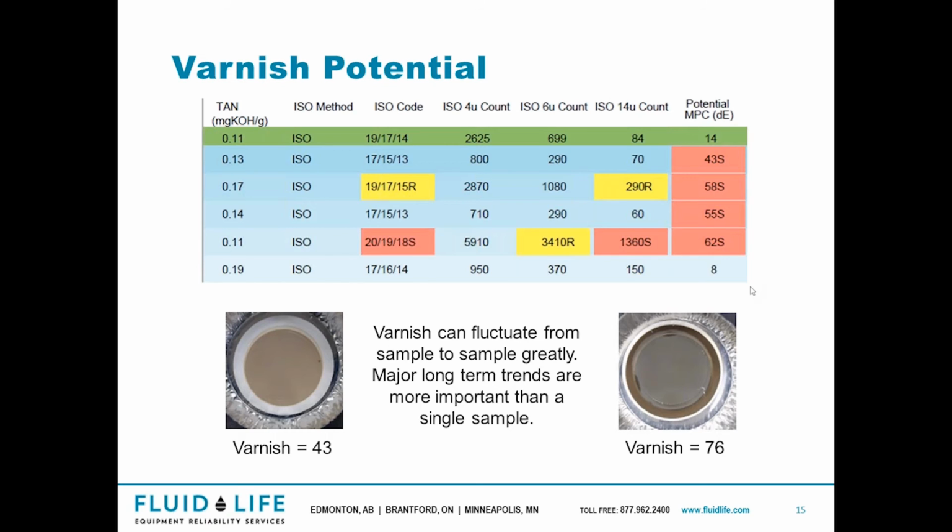You may also notice varnish in your tank. It often shows up as a sticky brownish gold bathtub ring inside of reservoirs. And so if you touch the side of your tank and your finger sticks, that is a sticky layer of varnish that's been deposited inside the tank because it's much colder than the rest of the system.